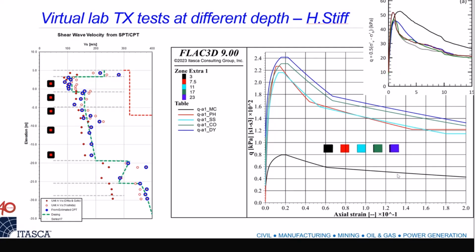So what I'm saying is that it is possible, I've done it myself, to include strain softening into the frame of the plastic hardening. And it can be done, again, by controlling the shear strain. Once you go over the peak shear strain or the peak axial strain, depending on if you're looking at the q or at sigma 1, which is equivalent, it's the same thing, then you can degrade the shear strength following a certain strain degradation curve, like you have here in the lab. Here I was trying to mimic, based on different lab data that I had for this triaxial test, just to show an example of how the system behaves.